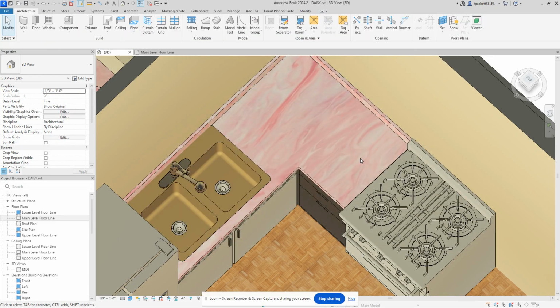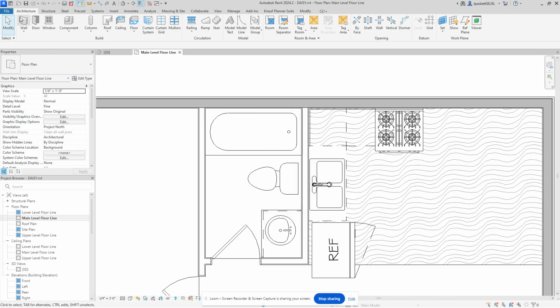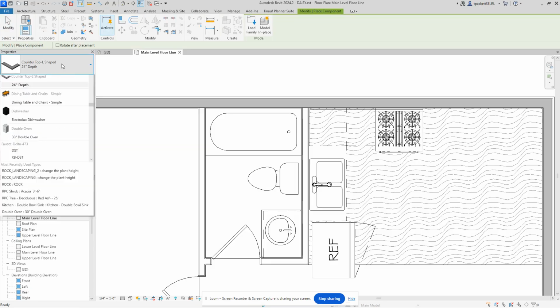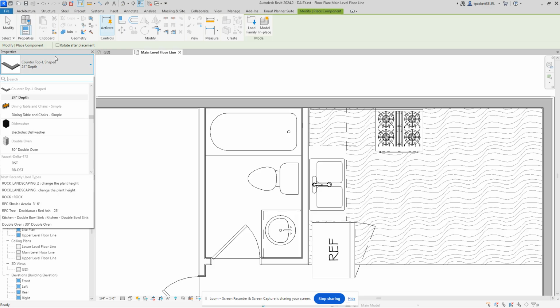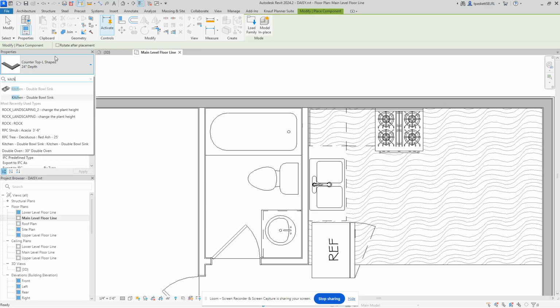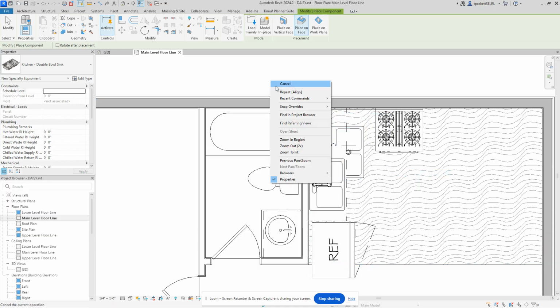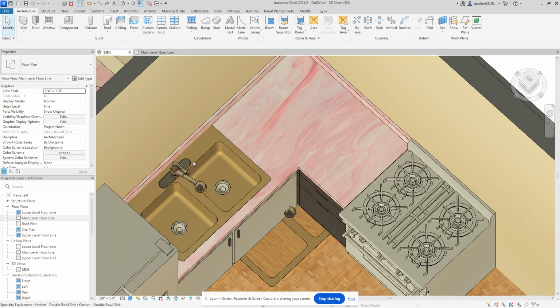No, can you walk through the sinks one more time? Placing the sink? Yes. Okay. So normally I would do it in 2D. The architecture component. Click in your select button here. Do a search. Now it's under kitchen sink. So I find my kitchen sink, activate that. I bring it over and I've got to tag the edge of the cabinet for it to show. Then I can rotate. And I don't try and push, I just try and get it attached. So once it's attached, and I'll show you that in 3D.